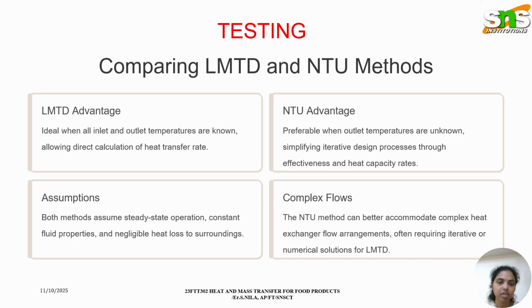The assumptions used here are that both methods assume steady state operation, constant fluid properties and negligible heat loss to surroundings. So how does complexity factor in? The NTU method can better accommodate complex heat exchanger flow arrangements, which often require iterative or numerical solutions for LMTD.